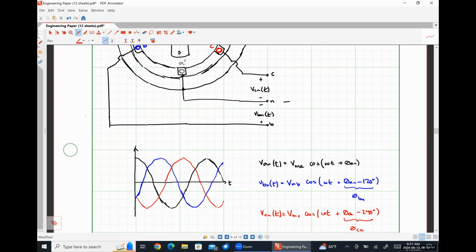They're literally the exact same thing, except that now, for a negative phase sequence system, C would lead B by 120 degrees, which would lead A by 120 degrees, and so forth. So the only difference it would make would be to change those signs on the minus 120 and minus 240 respectively. They'd go from negative to positive. So for the intents and purposes of this class, we are only going to be dealing with positive phase sequence systems because a negative phase sequence system behaves literally the exact same way. Everywhere you hear the word lagging, replace it with leading and you're done. Okay, so no real point in wasting a bunch of extra time on that.